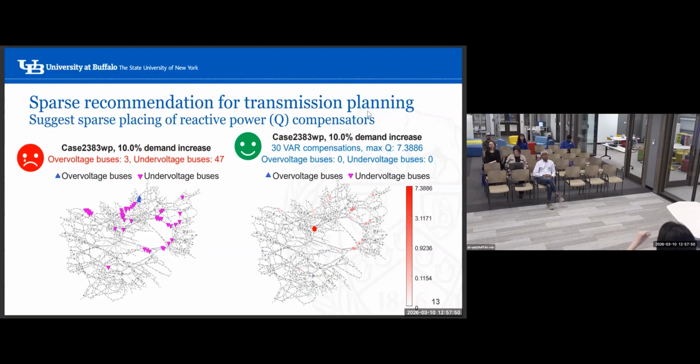It needs to operate under some particular voltage, for example, 110 volts. And also the power, where the power needed usually by the device is the real power, which we consume. But in the electricity field, there's also another power called reactive power. We do not consume reactive power, but reactive power is used to support the voltage such that the voltage is what we need.